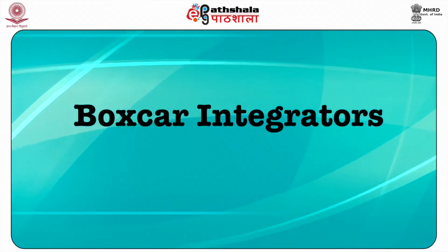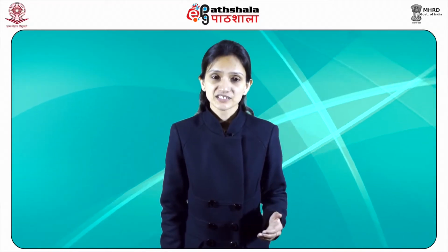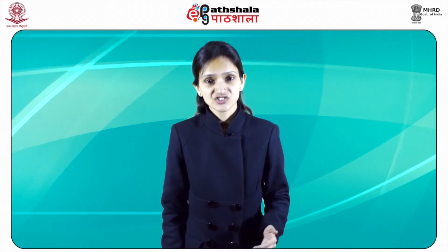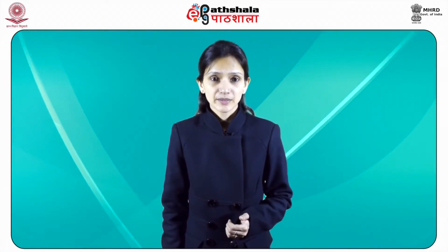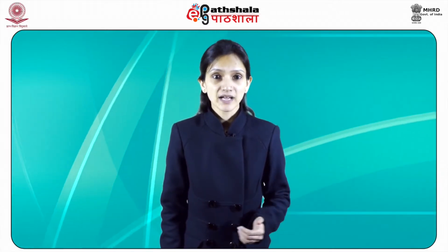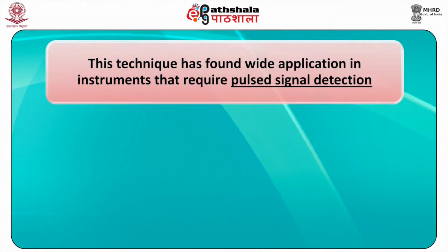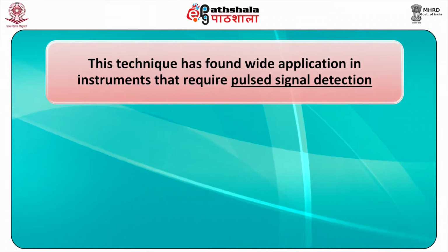Next is Boxcar integrators. The Boxcar integrator is a relatively simple method of signal enhancement for repetitive signals. It periodically samples the same portion of a signal for a fixed period of time and then averages the samples using a low-pass RC filter. This triggerable gated integrator is a versatile measurement device. It provides S/N enhancement for the portion of the signal that is sampled. This technique has found wide application in instruments that require pulsed signal detection.